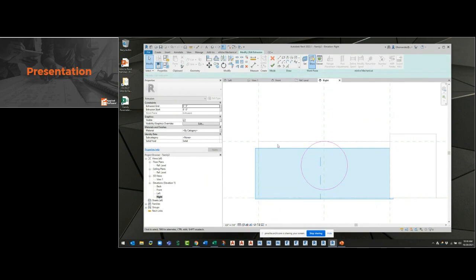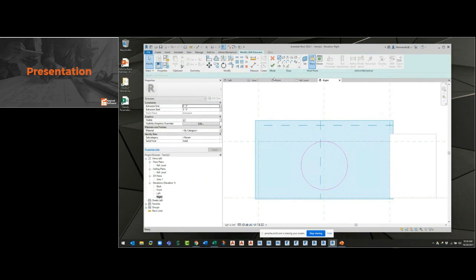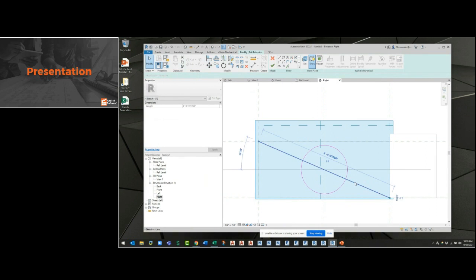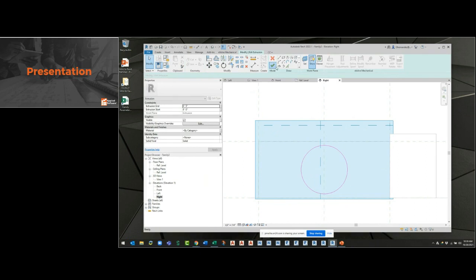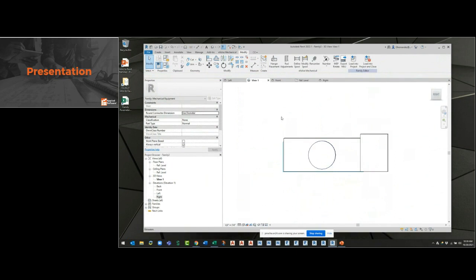I'm going to edit my sketch here. Make sure that I got this thing right at the center where I want it. Move it. Snap center to midpoint. Finish this out.